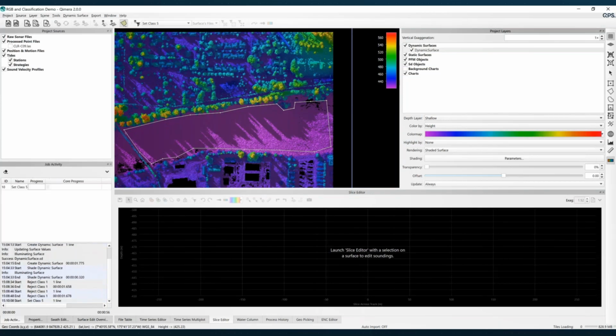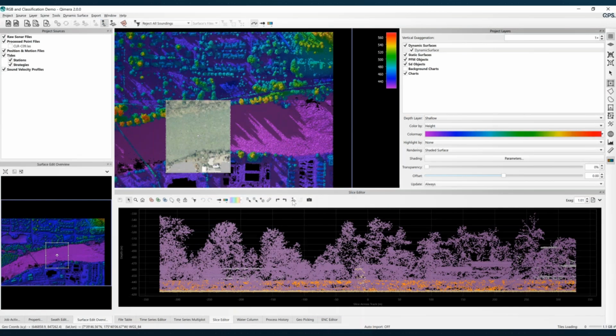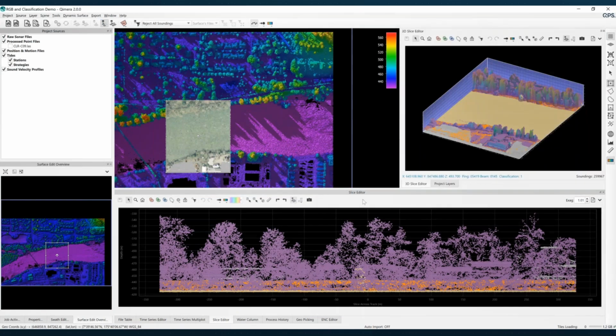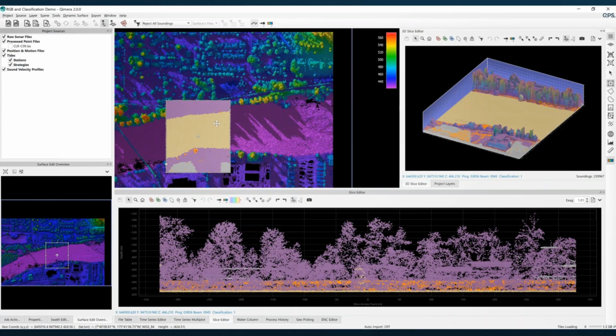And then that filter is applied. There's no actual effect on the grid because the Z values don't change at all. So if we come back to the slice editor, we can colorize by the class and see what that looks like in the editors now. So draw a rectangle selection, run the slice editor, and you really can't see it in the 2D slice view, but if you run the 3D editor, the 3D slice, you can. You see there's a new color on the river there. And if you look down at the bottom, you see that's reported as class 5. And you can see the same thing can be done in the scene. The river points are now classified as class 5, whereas the trees and other things have different classes.